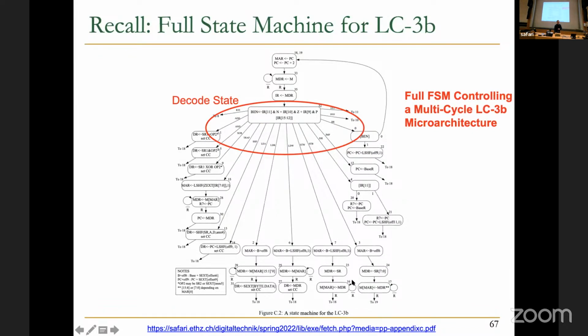Now, if you have a machine like this, you can also start adding states. For example, you don't have an instruction, you want to add an instruction. That's easy. You basically add another state over here after decode and specify the states that this instruction should go through. So you need to modify the finite state machine when you want to add an instruction. You need to provide the data path elements to process that instruction if they don't already exist. If they do already exist, that's good. You just need to specify the control signals to make sure the instruction gets processed through the states that you designed. And you need to add the control signals to process the instruction appropriately if they don't already exist.